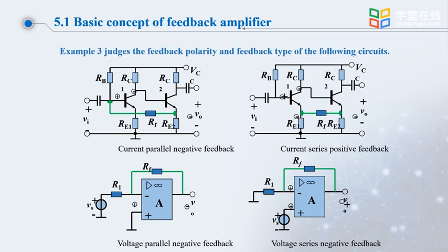On the side of signal input, the signal that connects to the basic amplifier is actually its reverse input. I give an instantaneous positive on the reverse input side. So the output port should be instantaneous negative, right? The reverse input is opposite to the output.